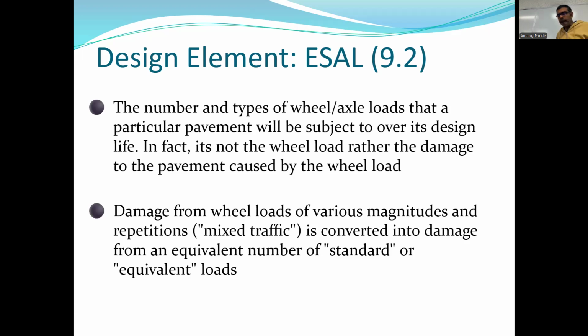Now, the relationship of the damage that the equivalent single axle load does onto the pavement is not a linear relationship. It's more of a fourth power relationship, okay? So again, it's the same idea. I think I showed you a chart very early in the quarter when we were talking about how the travel time increases as you add more traffic to the road. That's also an exponential formula, more like a fourth power formula.